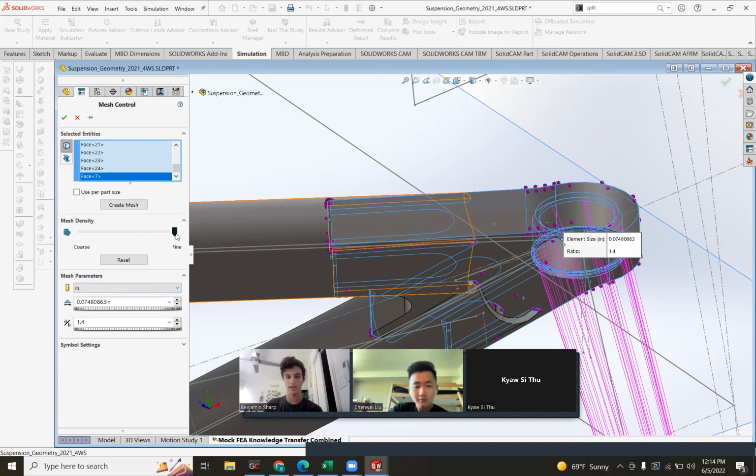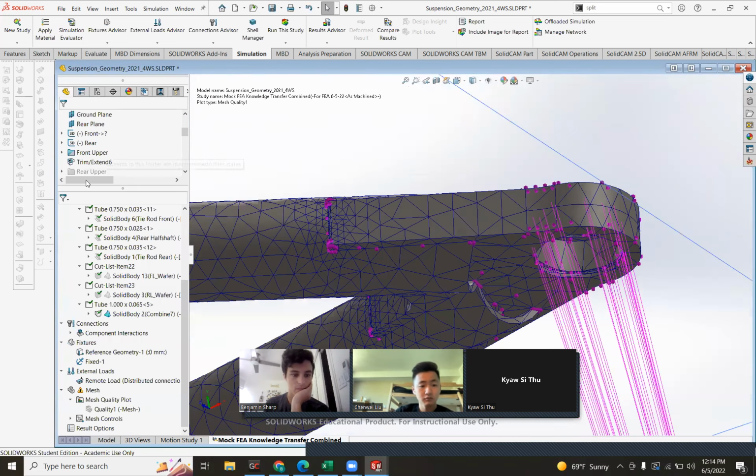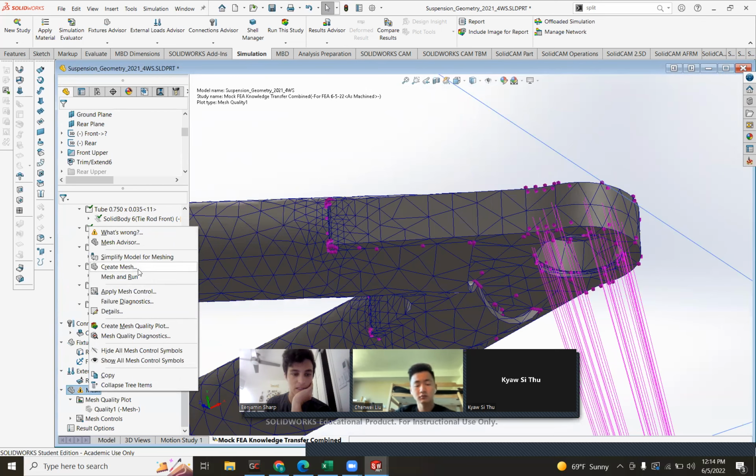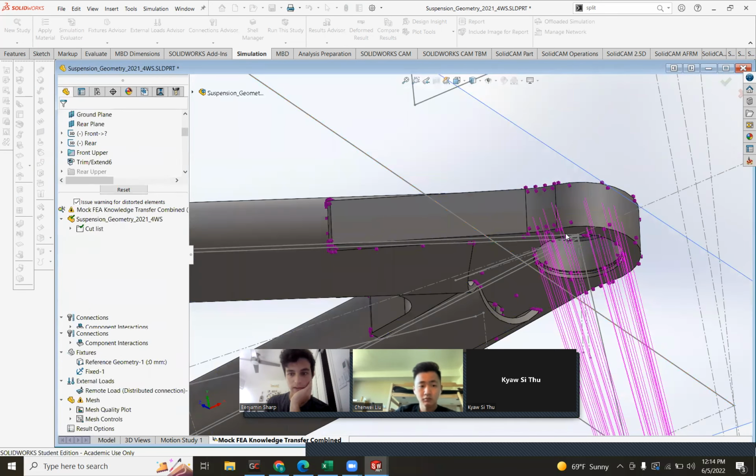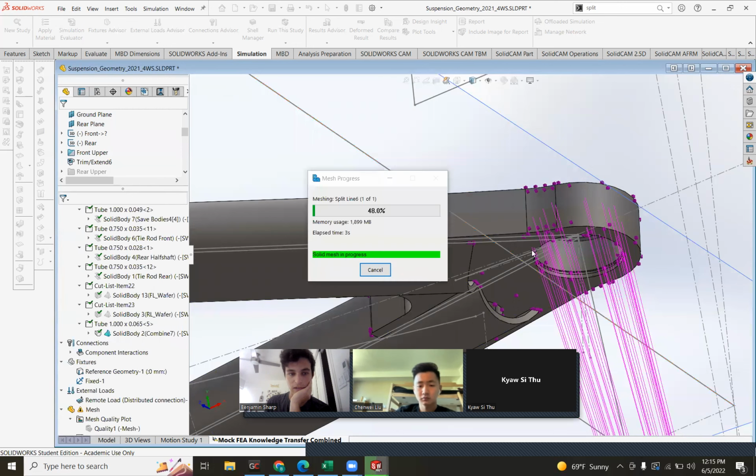Okay, so we're gonna make these just absurdly fine. And you can even go finer than this allows you. If you just type in a value, like we probably want less than 70 thou, we probably want like 20 thou. So we're gonna do that. And then we're gonna try to remesh. And this should look, if it works, way, way, way finer out on the wafer. But it's also gonna take longer, naturally. It has to think more.